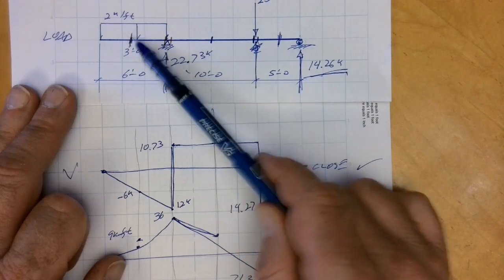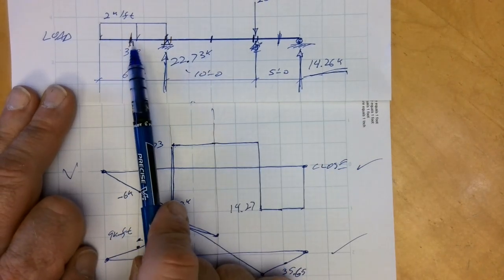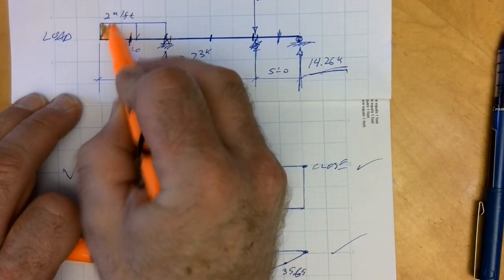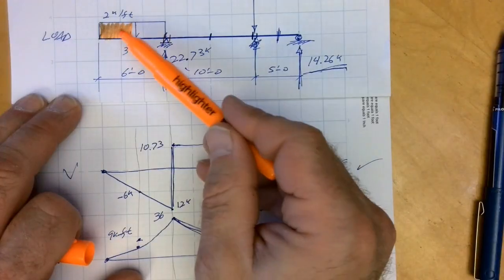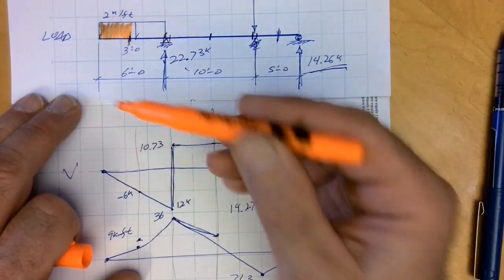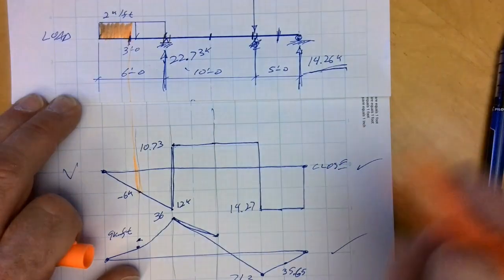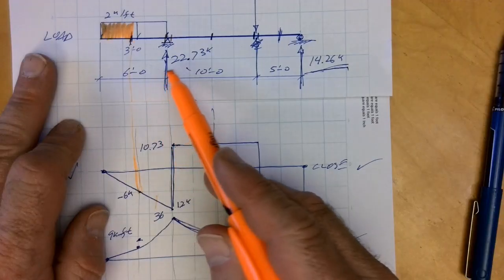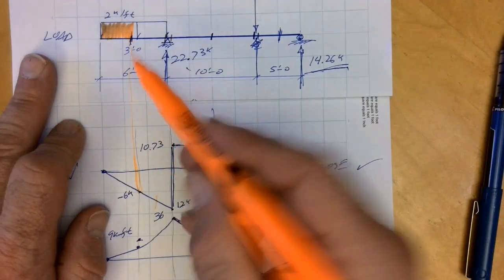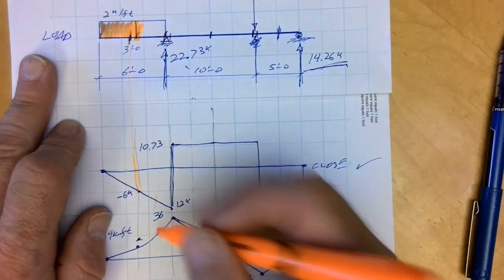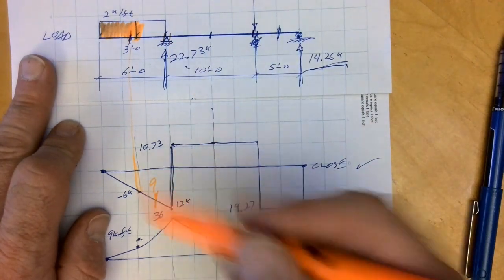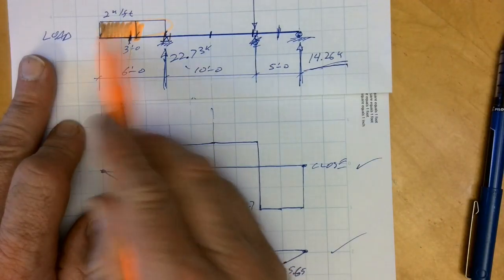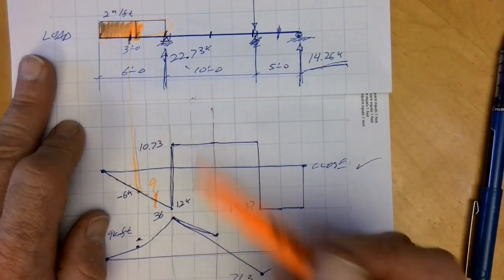So if I have a distributed load, anywhere along here I can find the shear by finding the area of that load. So if I come to 3 feet here, I can calc the area of that, which is just 3 times 2, which is 6 kips, and so that corresponds to here. I could come to this point at 4.5 feet, and multiply 4.5 times 2, and that'd be 9 kips and 12 kips. So the area of this gives me the magnitude at any location of x being horizontal.